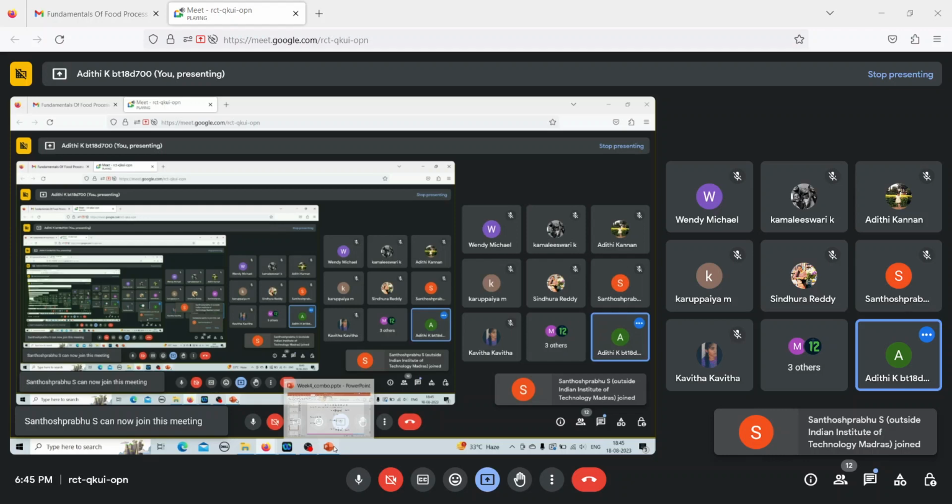So when you subtract it, that is the thickness that it has to travel, which is 0.02 minus 0.018, that gives 0.002 meters. That is your thickness. So we already have in the problem HO given, X is what we calculated, K is given, and HI is given in the problem. So I'm just substituting the values.